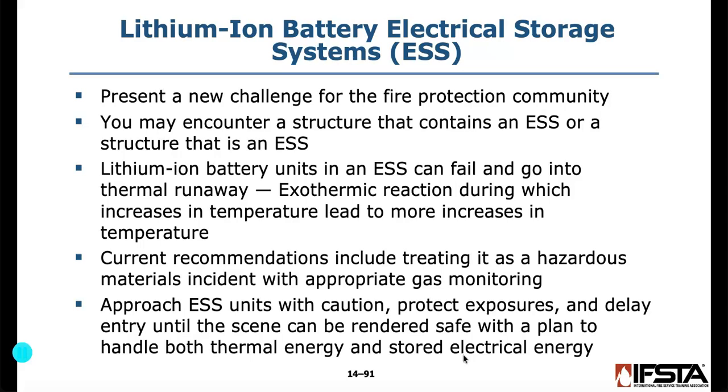You really want to remove that battery and then flood it, sink it into some kind of water and allow it to go out, right? So there's still an evolving way of fighting fires with lithium-ion batteries or energy storage systems. Essentially, what thermal runaway is, your lithium-ion battery starts breaking down, and when it breaks down, it starts heating up, and you're not going to stop that.